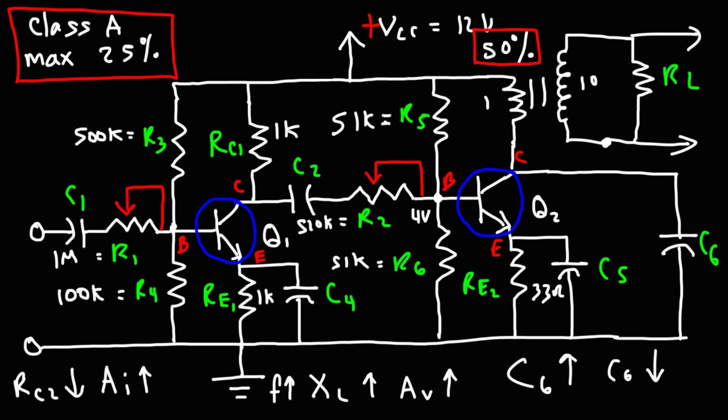So by adjusting C6, you can adjust the bass of the sound that you hear at the output. So you don't want C6 to be too high. Maybe like 1 microfarad or 0.1 microfarad should suffice. You can test out different values, but if it's too high, it will greatly reduce the voltage gain. So the voltage gain of the entire circuit will depend on the value of C6.